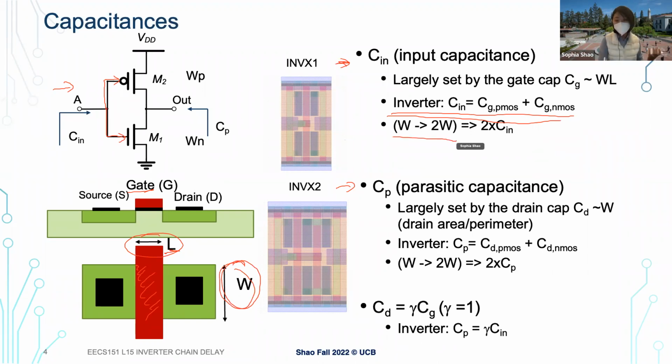So when we make our transistors bigger, more specifically wider, that also means we make our capacitance bigger, at least first for input capacitance, because I have a bigger cross-section area under the gate. We also see similar things with parasitic capacitance, because the width affects all the dimensions of our MOS transistor. So this is what people call input capacitance. This width dimension of our MOS transistor gives us a new parameter that we can change when we think about circuit delay. So that's width for input capacitance.